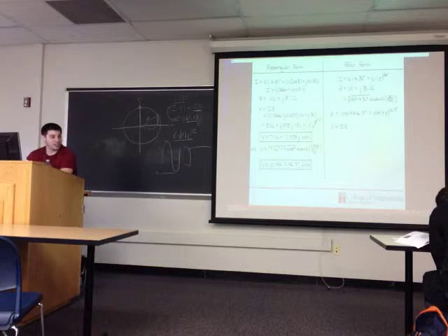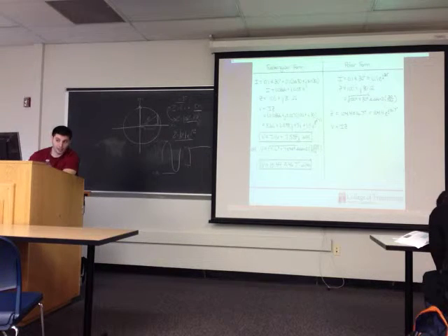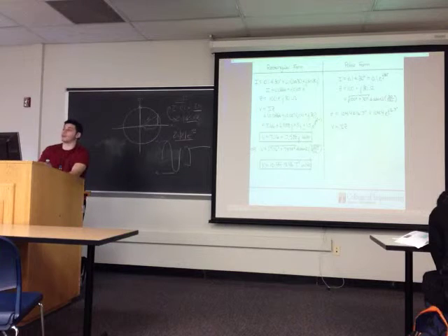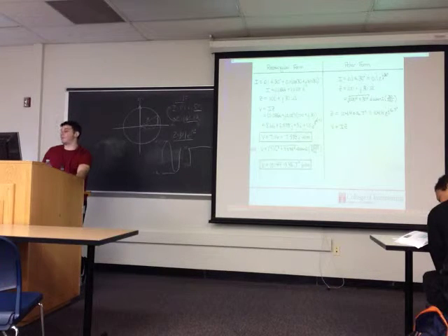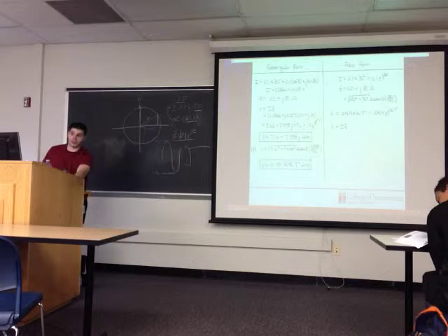Because essentially what V is also going to be in polar form. It's going to have a magnitude and an angle as well. We wouldn't add, but we would multiply our magnitudes, right? That would make sense to multiply our magnitude of I, which is this 0.1, times the magnitude of Z to get our new magnitude. But for our angles, it's a little different. We're going to add our angles. So multiply the magnitude, add angles. If it's division, you're going to subtract angles.